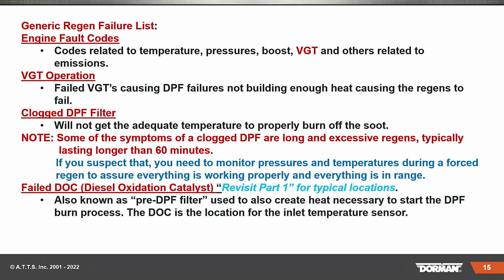Don't forget you've got the diesel oxidation catalyst too, okay? Revisit part 1 for typical locations. You can also look at it as a pre-DPF filter; it helps create the heat necessary to start the DPF burn process, okay? And the DOC is the location, many times, for an inlet temperature sensor.